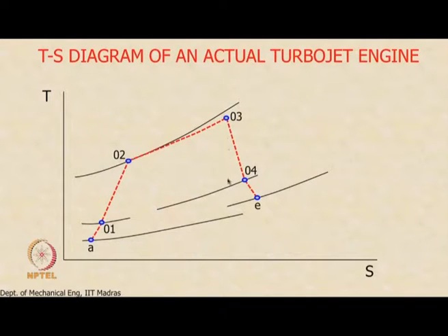So, whatever work we are getting now is going to be less than whatever we could have obtained earlier. Because of the irreversibility, then here you see expansion in the nozzle, and similar to what we discussed for the other components, the expansion process for example will give only slightly less velocity than what we would have obtained had the process been isentropic.